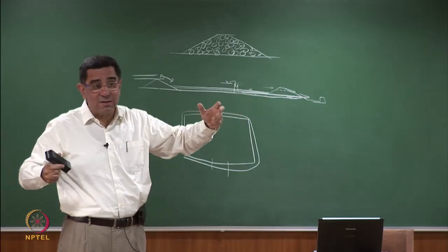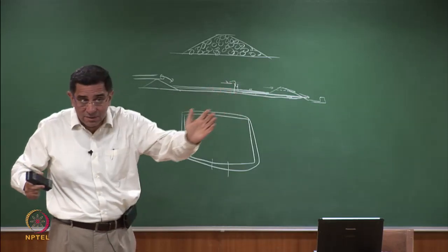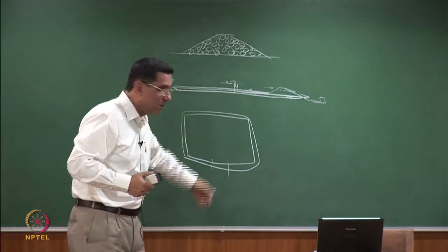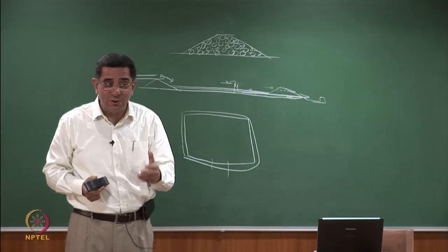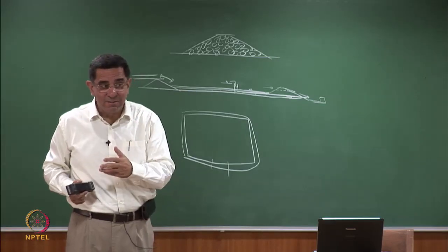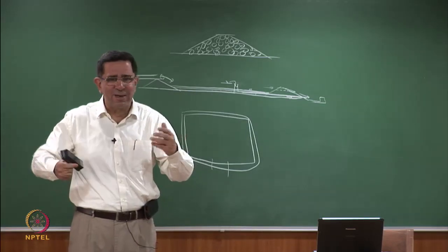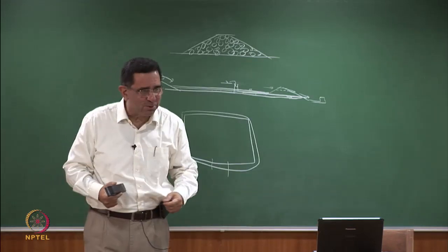No, total material is silty sand. Towards the inflow is here, outflow is here. What's the material coming in? More silt. So you need a filter between a silt and cobble. Oh, that's a lot of filters. Immediately, how many filters do you think you would like to put?